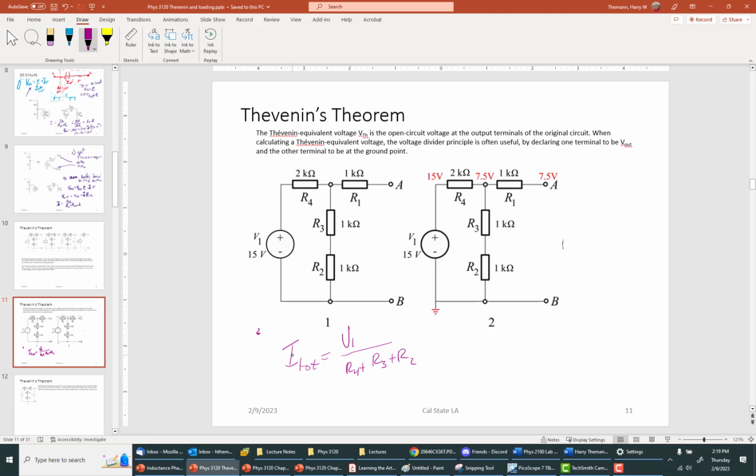Notice we're not doing any voltage divider equation. I'll show you that in a minute, but the brute force way is just as in any other circuit, or the original way we looked at the voltage divider. Notice that R1 is not in that circuit, because no current can flow through R1 since it's open, the so-called open circuit voltage, which is also what we get when we use an ideal voltmeter.